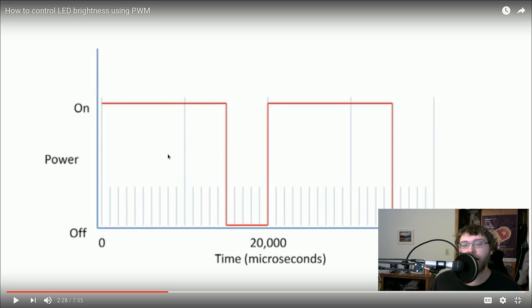And so this is the other thing that kind of threw me off, I guess, is we don't actually need to think about the waveform that we can create with PWM. We can use PWM to represent these analog waveforms, right? Like a sine wave. But for our purposes, what we're doing here with controlling an LED, we don't even need to think about waves. We just need to think about what they're showing right here with these pulses, where how much it's on directly affects the brightness that we're getting.